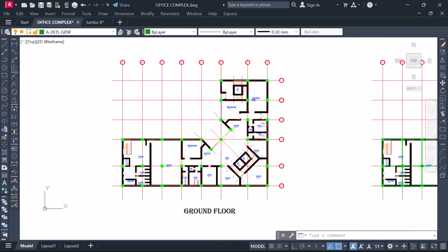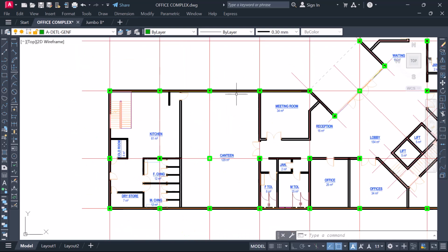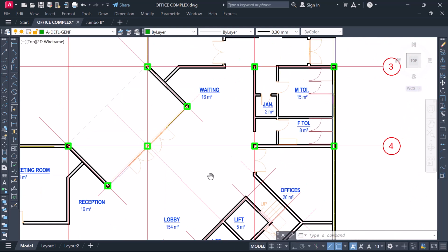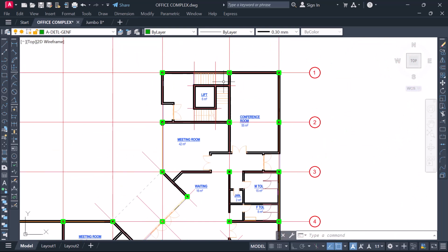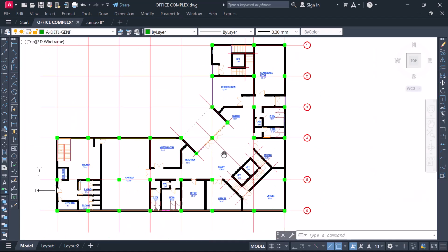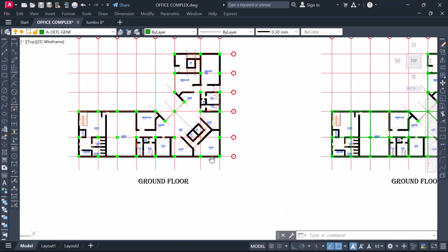How do you know where to place a column or a structural member to carry what you understood on the building plan? So you can see why understanding the building plan is number 1. It's the first step. So step 2 is preparing your structural framing.